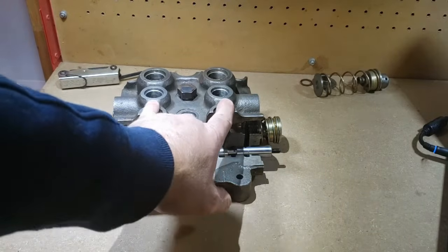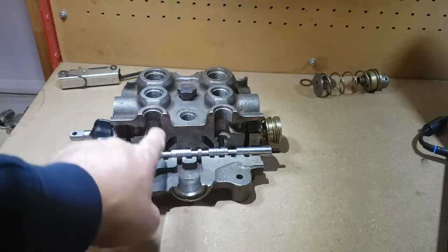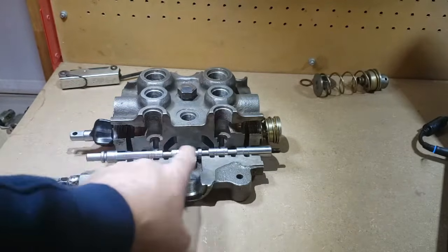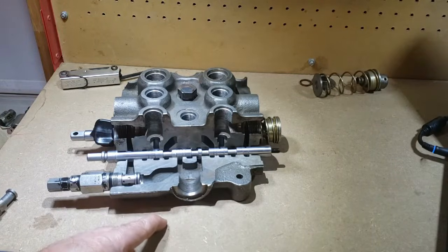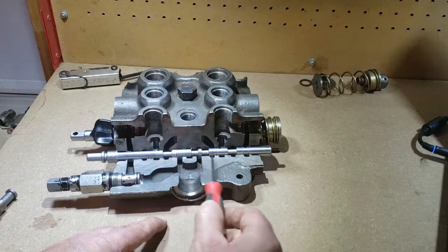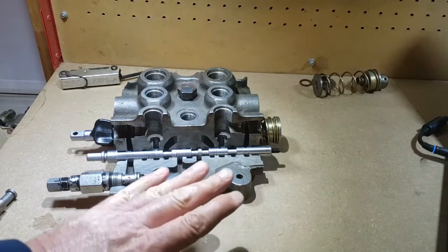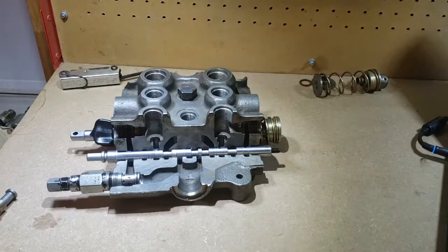So there's no more trapped oil in our work ports of our cylinder. The oil is free to travel from the rod end of the cylinder to the head end and vice versa through the hollow spool. So oil can travel in here, across here, or oil can travel in here or across here. And that's going to allow the implement to float as we drive the machine forward. No longer is there trapped oil on either side of the lift cylinder, so the loader frame's not rigid to the machine frame.